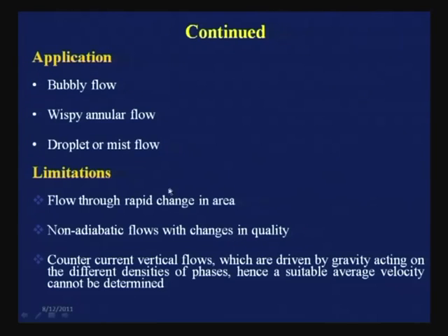I had just mentioned this, but I had not given the specific examples: flashing of steam water mixture through short nozzles and orifices, bubbling in superheated liquid, supercooled vapor condensing in high velocity steam, and particles of solid propellant burnt in nozzle of rocket engines. Under these situations, there is rapid acceleration and rapid pressure changes, and we cannot use it.